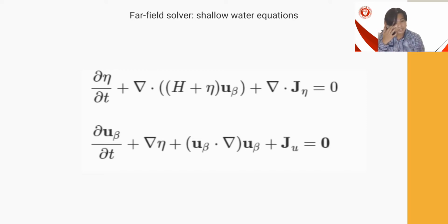The pressure p is replaced by the free surface elevation, eta, and the velocity u is substituted by the mean horizontal velocity U. The equations are an extension of the SW equation, or shallow water equation, which include the modeling of the frequency dispersion for long waves.